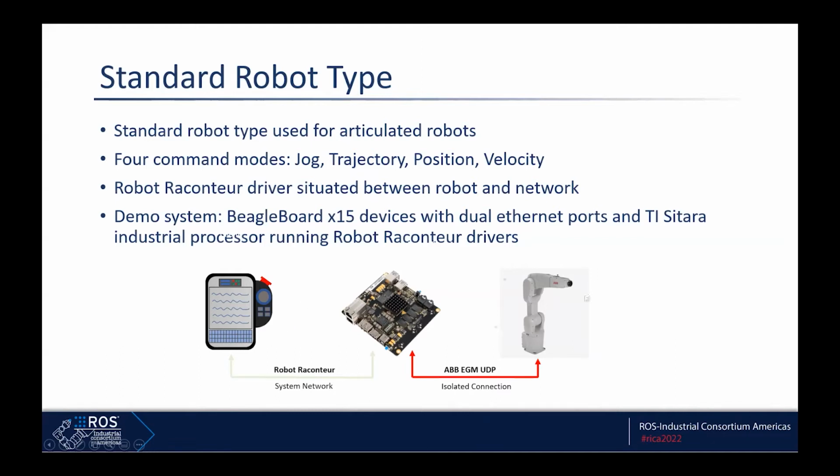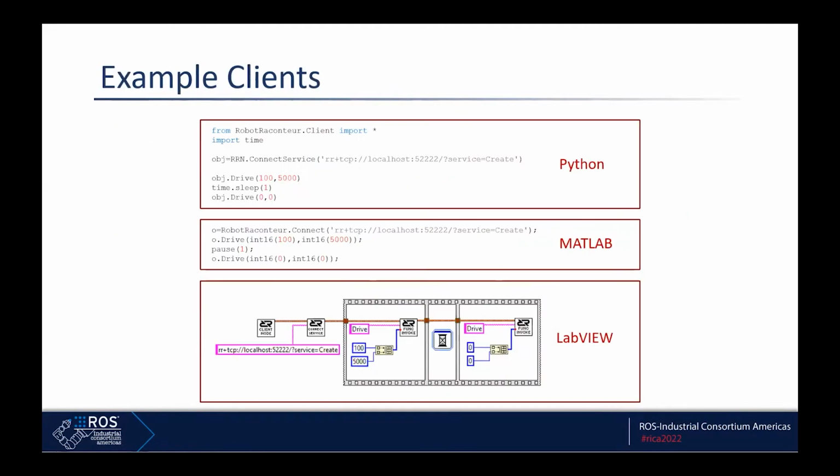So we often will put a collection of ROS nodes behind a Robot Raconteur service and then have it available as a standardized type. Now, this can either be done using the ROS bridge or with a bridge specifically designed for the application, so it can have the desired typing for that standard interface.